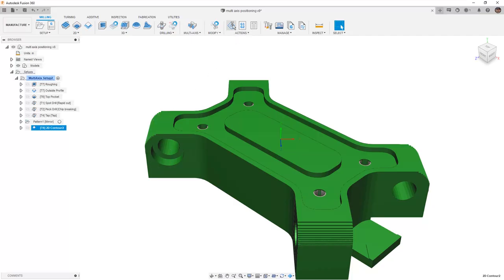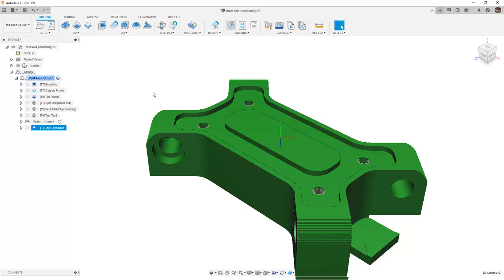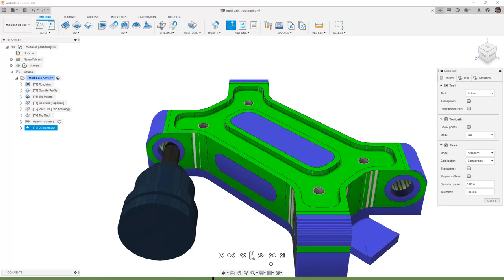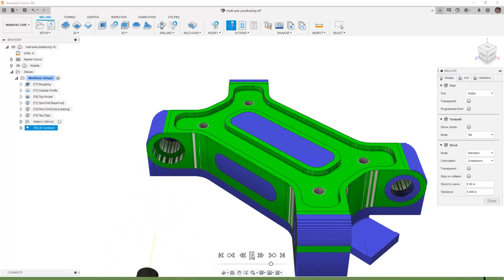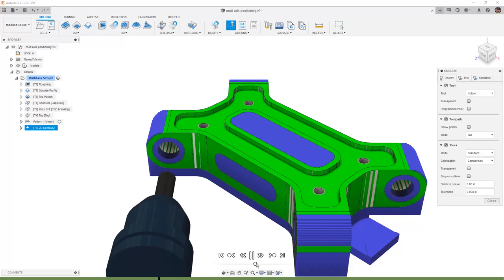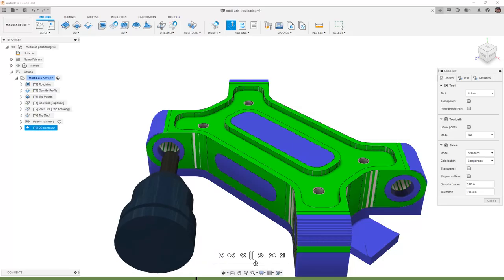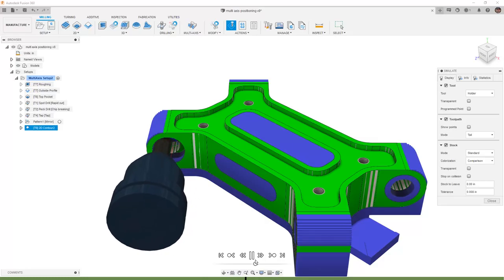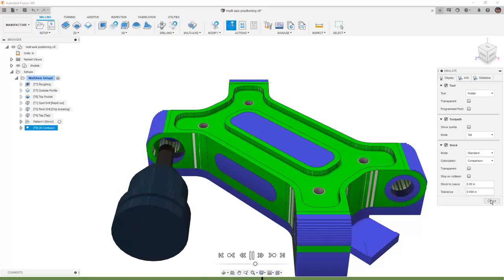But before we go ahead and create duplicates, let's take a look at what is actually being machined with that operation. So the tool comes in, you can see that it plunges, and then it creates that pattern. We're going to go back to the previous operation and play through again, but this time I want to slow it down a little bit. I want to see how it engages the stock to see if we need to add a roughing pass. As it goes in, it's actually machining, which tells me that it's removing too much material in this single pass.